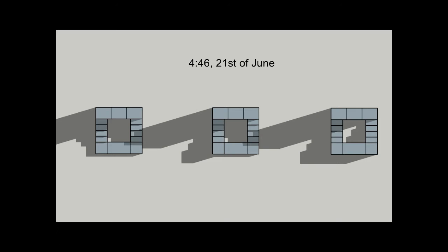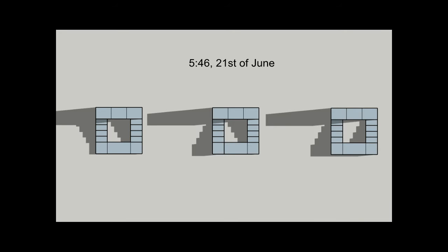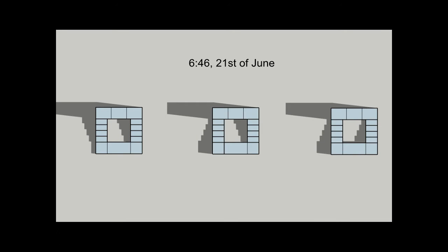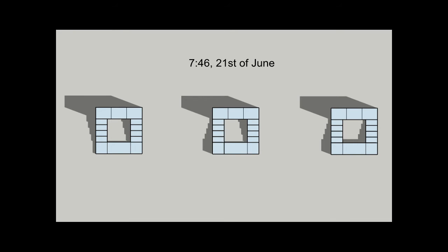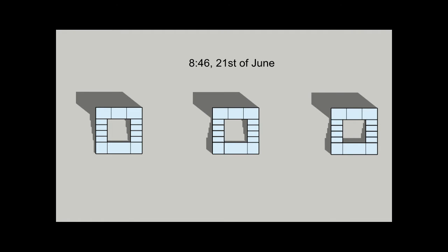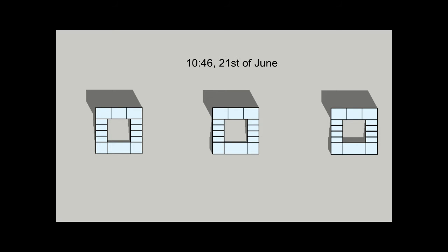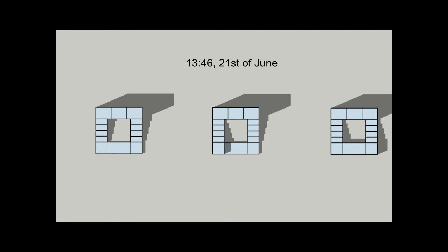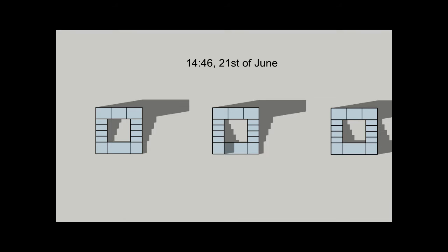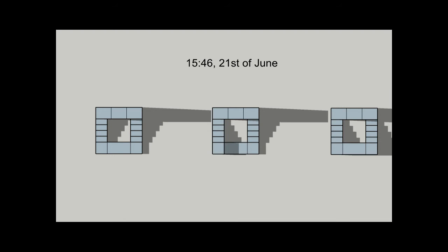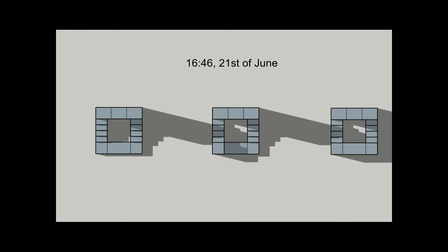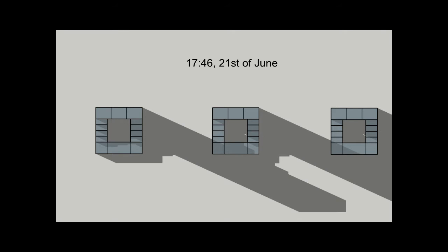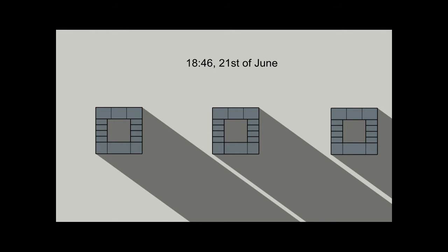The shadow analysis showed that between 7:46 and 15:46, option 3 casts more shadow into the courtyard. Option 2 also casts slightly more shadow into the courtyard than option 1, though the difference is very small. Overall, the height of the building is directly proportional to the amount of shadow cast. As you can see from the analysis, the tall buildings towards the north, because of their position, cast very little shadow into the courtyard. Option 1 was chosen because in this option, most taller buildings are placed towards the north, which as a result, casts less shadow into the courtyard.